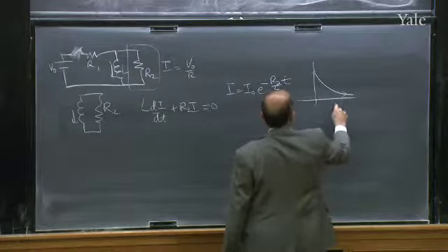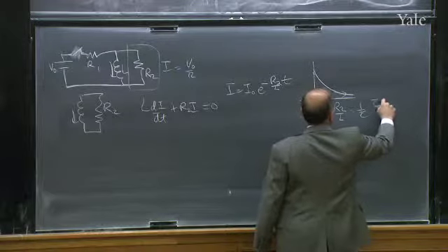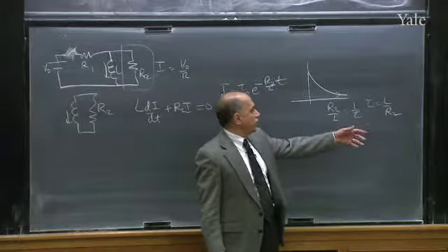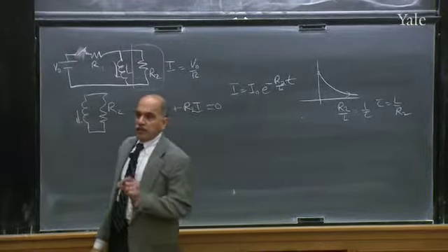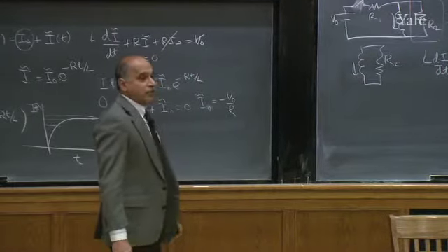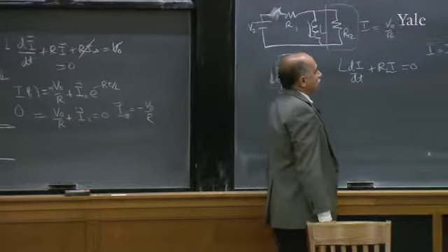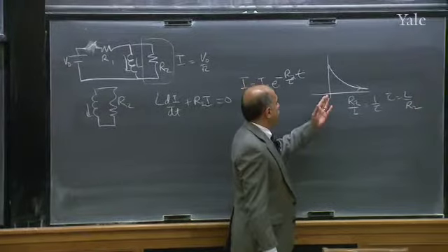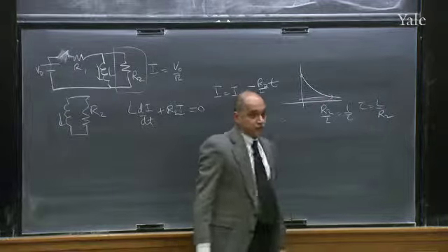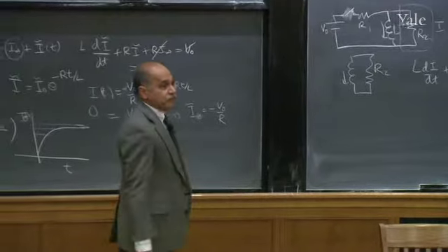So now the current will decay exponentially, again with the time constant, R2 over L, which is 1 over the time constant, or the time constant is L over R2. So you put L in henries and R in ohms, you'll get some time. That'll give you an idea of how many times that time you have to wait before the inductor is completely discharged. Well, it's never going to be fully discharged. It's going to take forever. But if you say, look, 1,000th of the original current is safe enough, how long do they have to wait? You put 0.001 here and see what time you get. So you want e to the minus t over tau to be 0.001.